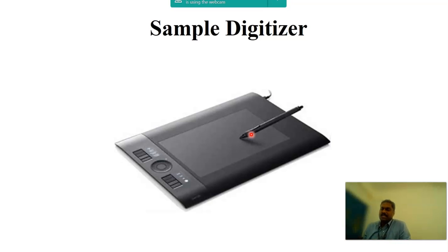Many graphic tablets are constructed with a rectangular grid of wires embedded in the tablet surface. Electromagnetic pulses are generated in sequence along the wires, and an electronic signal is induced in a wire coil in an activated hand cursor to record a tablet position.